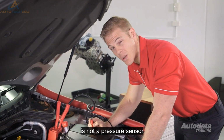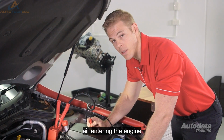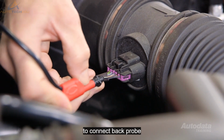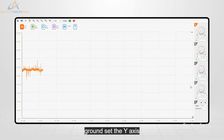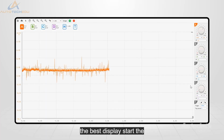The airflow meter is not a pressure sensor, but is a device that measures the amount of air entering the engine. So, while we're in the area, let's scope this too. To connect, back probe the sample lead to the signal circuit of the airflow meter and the black lead attached to a known ground. Set the Y-axis to 10 volts and the X to 1 second for the best display.